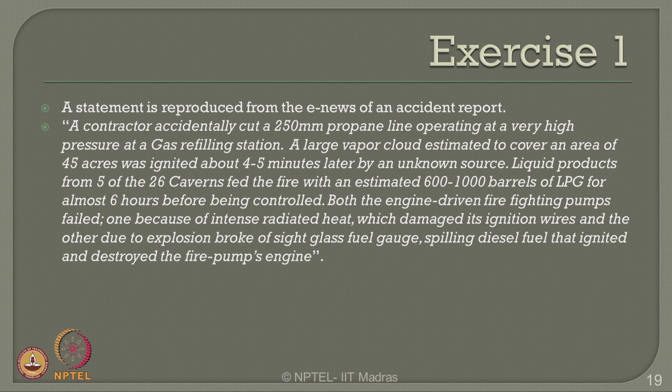Both the engine driven firefighting pumps failed, one because of intense radiated heat which damaged its ignition wires, and the other failed because the explosion broke the side glass fuel gauge, which resulted in spilling of diesel fuel that ignited and destroyed the fire pump's engine completely. This is a very interesting accident statement which is reproduced from a news report.